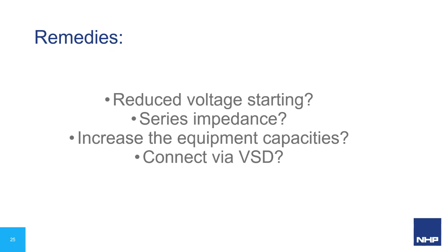Do we increase the connected equipment capacities? Well, yes, this has proven to be successful. However, it may be expensive in relative terms, especially in smaller kilowatt applications. So do we connect via VSD? Yes. Well, the VSD is the most successful method of overcoming the problem of the motor start. It also gives good torque control throughout the start and run process. The VSD itself, however, is not 100% efficient.